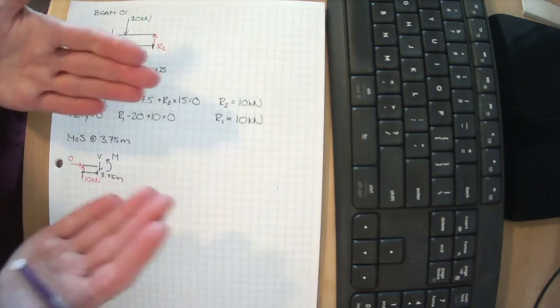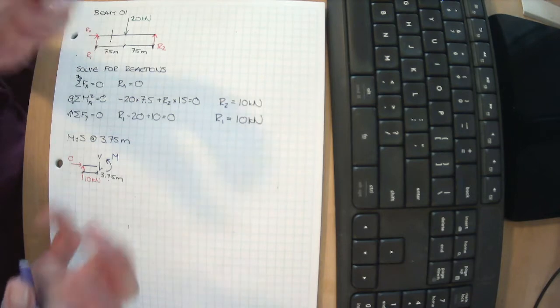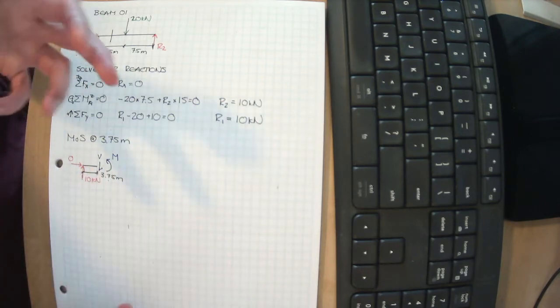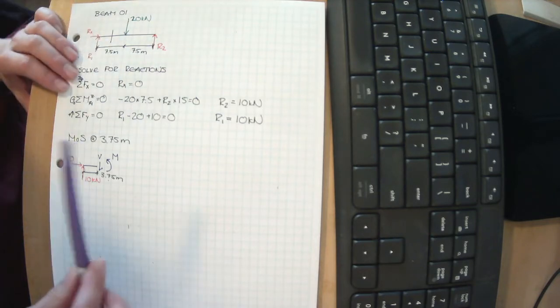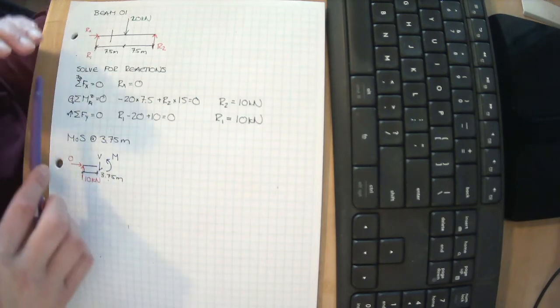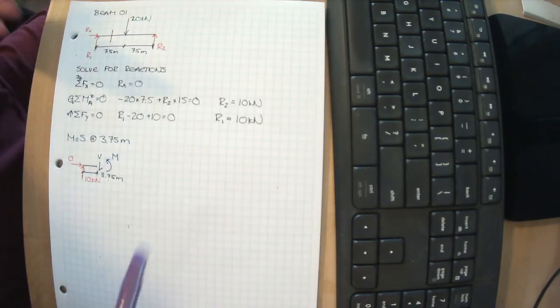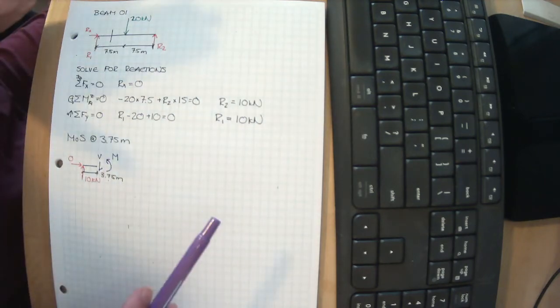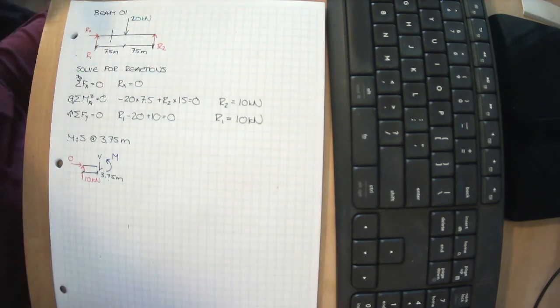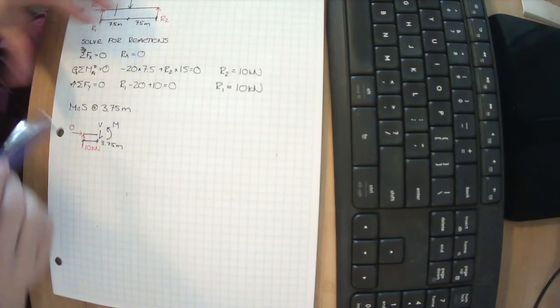So tension and compression have really different effects on what happens within our structures, especially for material design later on. Shear, we actually don't care that much if it's positive or negative. It doesn't have an implication on how the material behaves. Shear is shear. But keeping track of positive versus negative is important because it tells us where we cross datums. So the only reason we care about a positive or a negative value in shear is to complete our methodology. But once we get all of our answers and everything solved, a positive versus a negative is absolutely meaningless to us. And you'll see what I mean when we get to that.